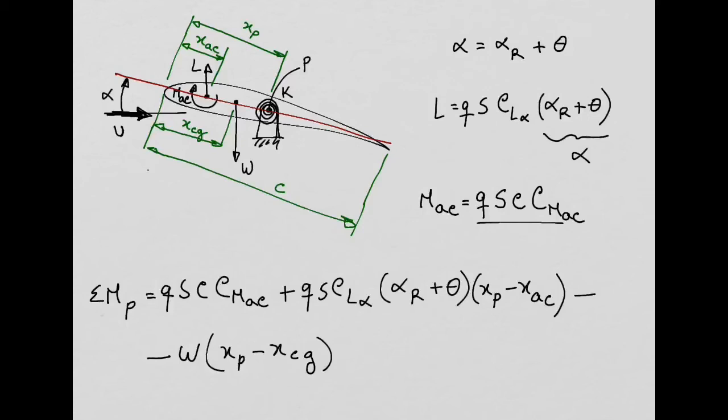And that moment is equal to, so nose down means negative, first of all, the torsional stiffness, which is K, times the torsional angle. And that torsional angle is not alpha r. Alpha r is the aerodynamic angle of attack. So when the airfoil rotates due to torsion, the angle we need to consider is the aeroelastic angle theta, right? So I need to multiply this K by theta. And this will give me the torsional moment. Make sense or not?